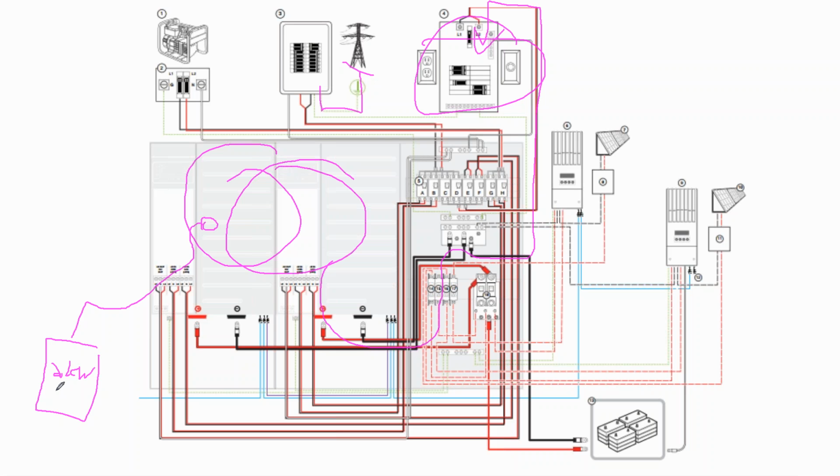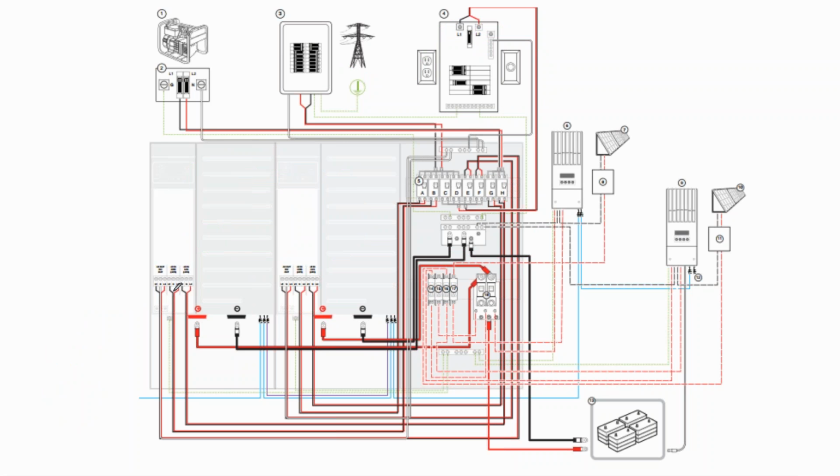If you have a 1 megawatt facility and you're only doing a 100 kilowatt commercial solar peaker, you're still going to have that critical load panel and not be able to supply the entire building during that blackout. You would have to have a 1 megawatt output to supply the entire building.